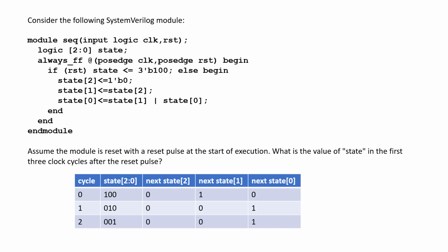And by the way, the reason I mentioned this was a little confusing is because when I'm saying next state, there's only one variable called state, right? But the next state is what's being set on the left-hand side of the assignment, and the current state is the stuff on the right-hand side of the assignment. Because in Verilog, these are separated based on the behavior of the always. So the always will run, and after it gets done running, it'll set up the new state. But it's always looking at the old value and then setting a new value. So when I say next state, I'm really talking about state, but it's what you're assigning state to be. Just to clarify that.